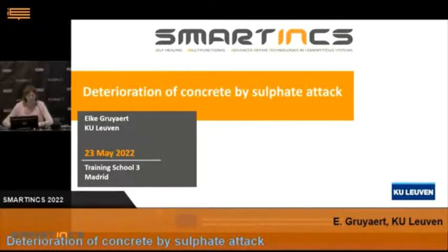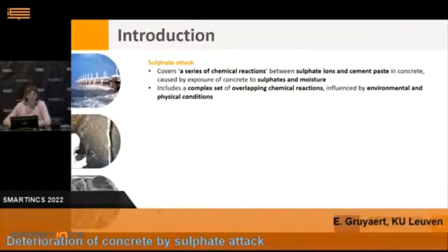Okay, we will start about sulphate attack in concrete. So I'm very happy that the colleagues just before me in the program have introduced again the cement chemistry, the hydration of cements and so on, because we will really need it here in the presentation. So first of all, sulphate attack covers a series of chemical reactions between sulphate ions, of course, and the cement paste in concrete, and caused by the exposure of concrete to sulfates and moisture. And it's really a complex set of overlapping chemical reactions.